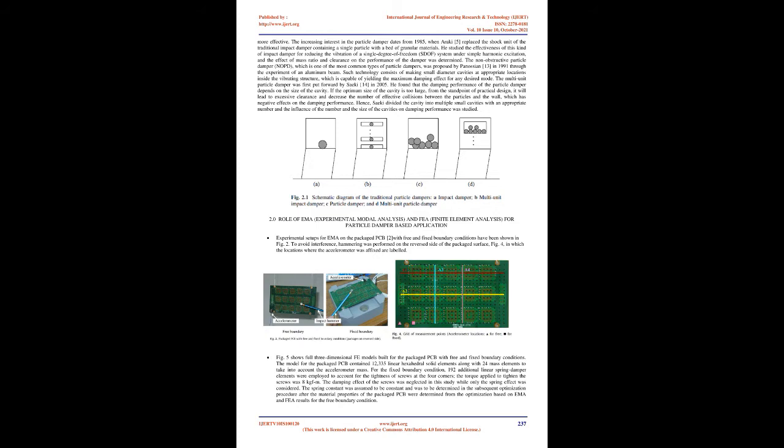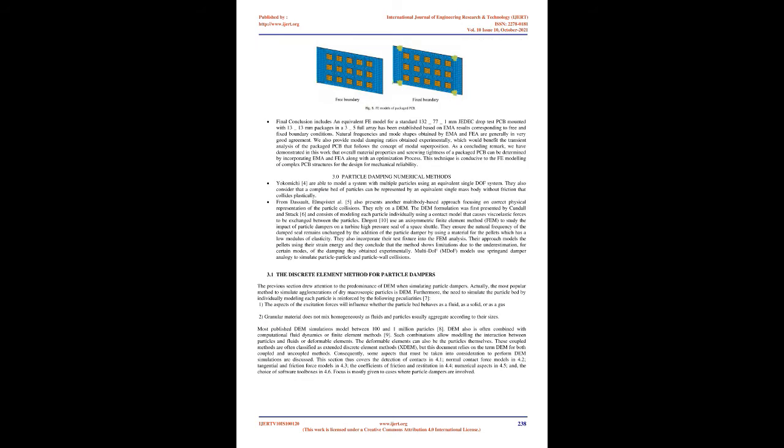Fig 5 shows full three-dimensional FEM models built for the packaged PCB with free and fixed boundary conditions. The model for the packaged PCB contained 12,335 linear hexahedral solid elements along with 24 mass elements to take into account the accelerometer mass. For the fixed boundary condition, 192 additional linear spring damper elements were employed to account for the tightness of screws